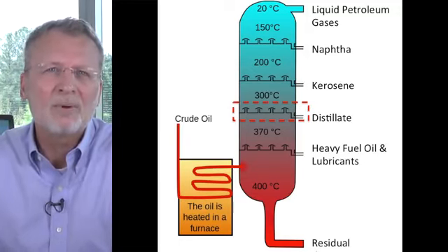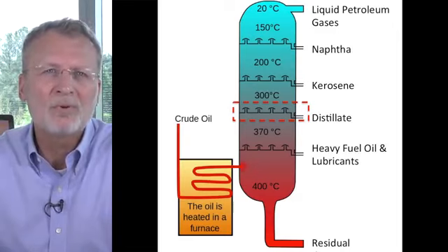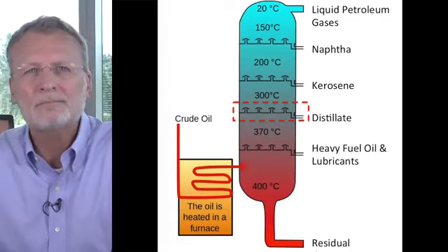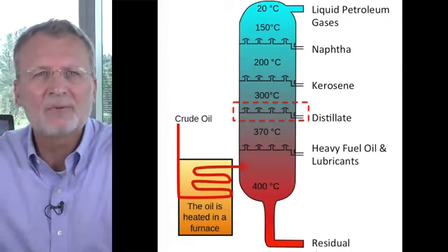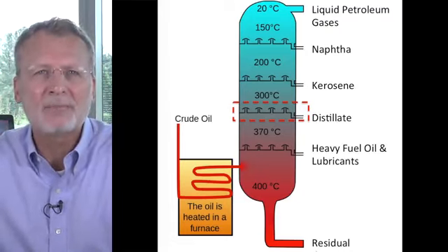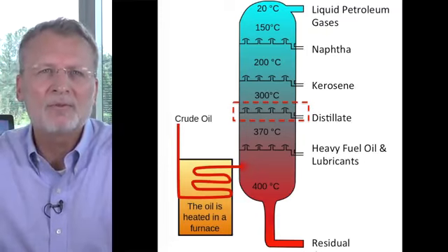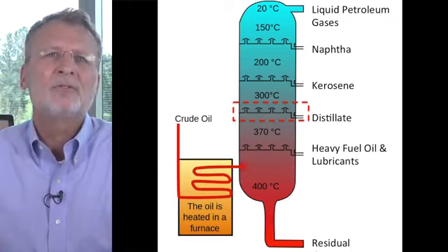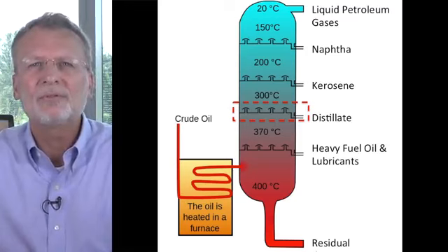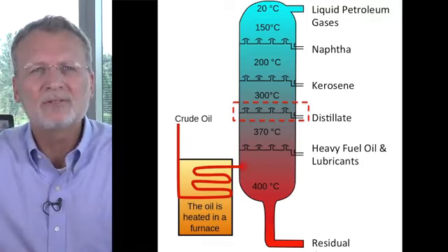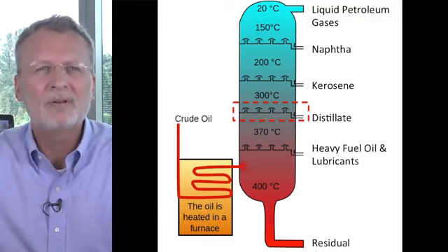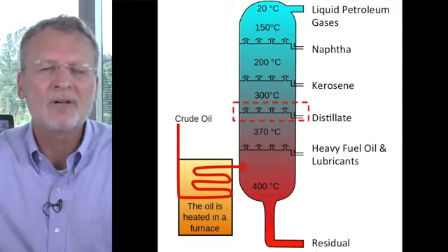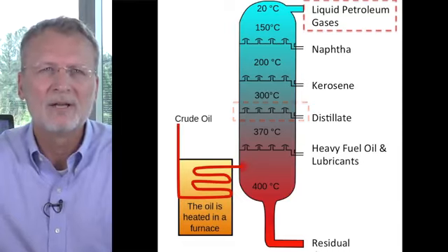These trays are punctured full of holes that are topped with bubble caps, which act like a loosened cap on a soda bottle. Rising vapor passes through these holes and out from under the bubble caps, the edges of which drip those hydrocarbons that precipitate out at that particular temperature in the distillation tower. The trays direct the separated streams of fluid hydrocarbons out of the distillation tower to other units in the refinery where the separate hydrocarbons often undergo further processing.